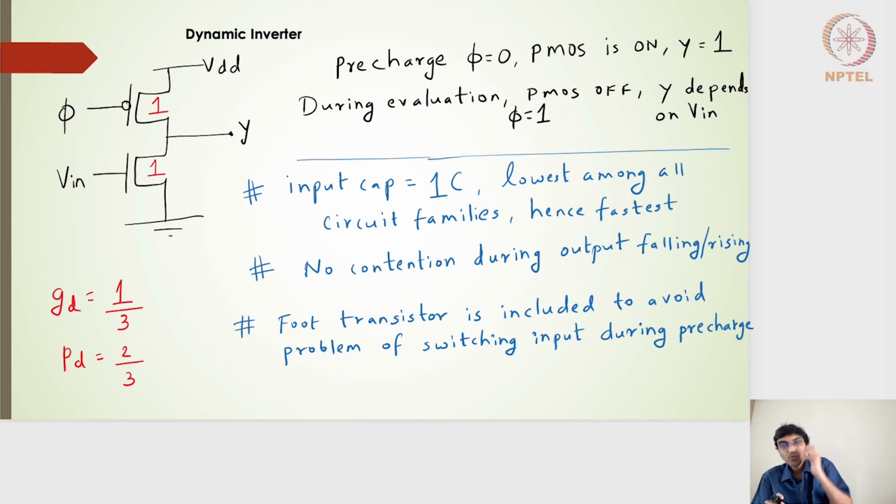So that is one set of logic family, the Ganged CMOS, and it is very applicable to NOR gates, and it is implemented only for NOR gate circuits. Another very useful circuit is the dynamic logic, and I have drawn here the dynamic inverter. Let's talk about how this inverter circuit works. I have a PMOS transistor with a width of 1, and then an NMOS transistor with a width of 1. Input is applied only to the NMOS side, and a clock is provided to the PMOS side.